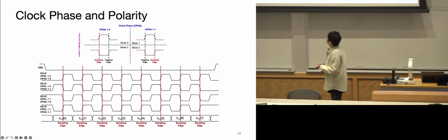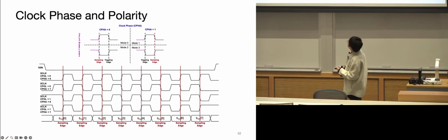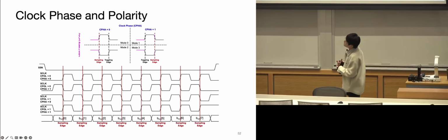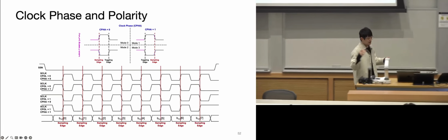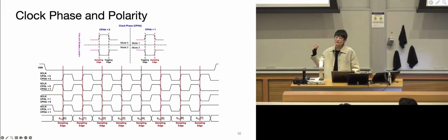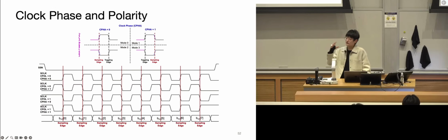Yeah. How does a peripheral, on the previous slide, how does a peripheral generate an interrupt? Can it generate interrupts? It can. It's usually generated through the controller. So the signal goes to the controller, and then the interrupt is generated from there to go back to the core. Yes, and the peripherals that are connected essentially chip to chip don't directly talk to the core for the interrupt.